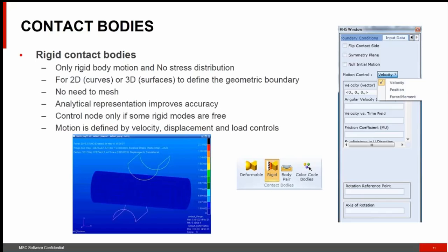And generally within the analysis, these rigid surfaces are treated, as I mentioned, in two methods. There's the discrete or the analytical one. And I think Patran does the analytical one. The discrete one consists of patches or straight segments, whereas the analytical one is more continuous and more smooth.